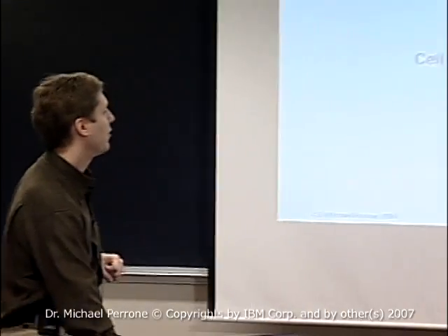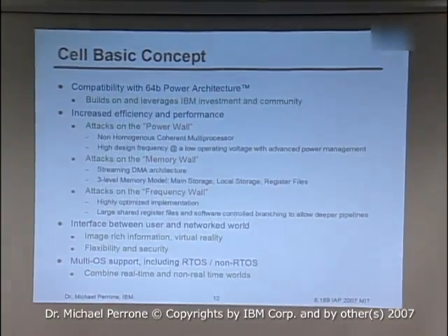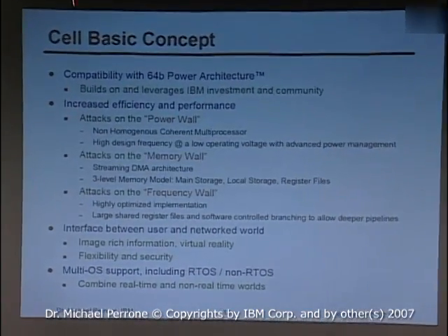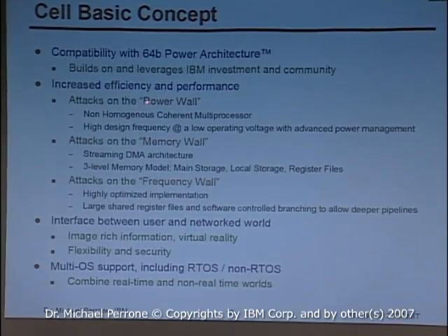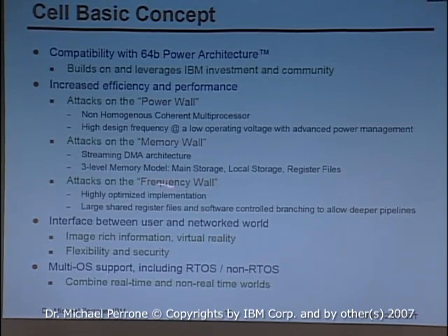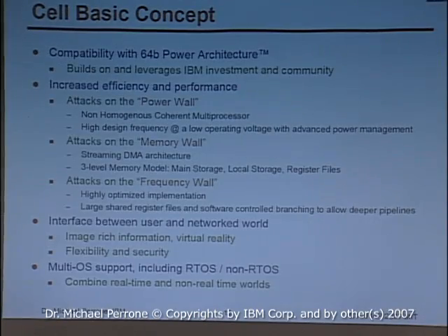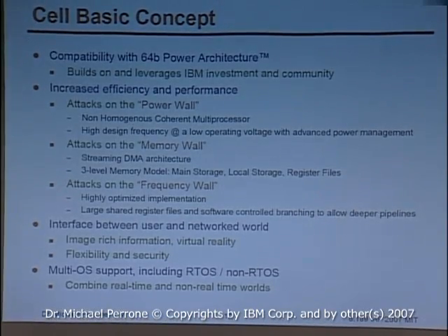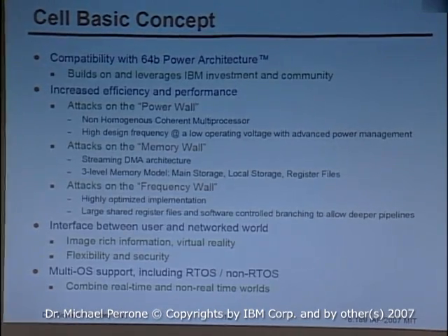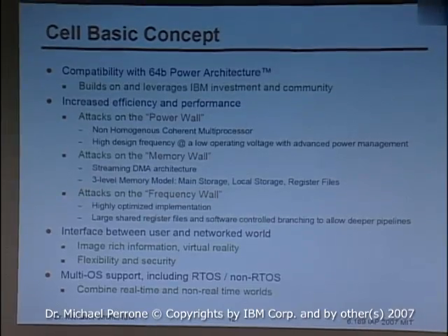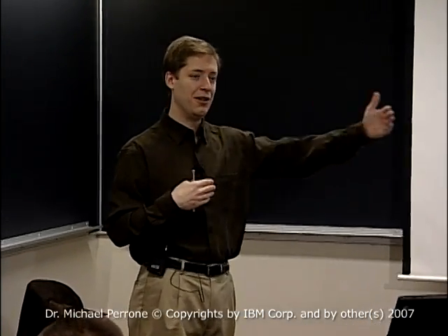All right, so let's talk about the design concept. Here's a little bit of a rehash of what we discussed with some interesting words here. We're talking about a power wall, a memory wall, and a frequency wall. So we've talked about this frequency wall. We're hitting this wall because of the power, really. And the power wall, people just don't have enough power coming into their buildings to keep these things going. But memory wall, Saman didn't actually use that term, but that's the fact that as the clock frequencies get higher and higher, memory appears further and further away.